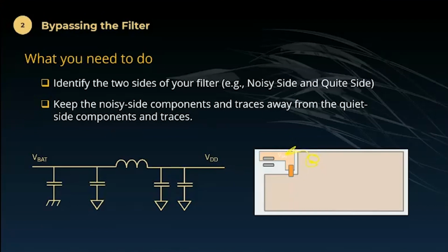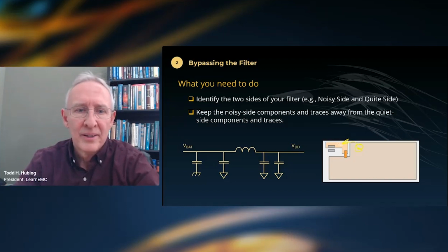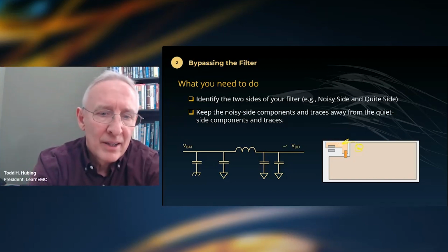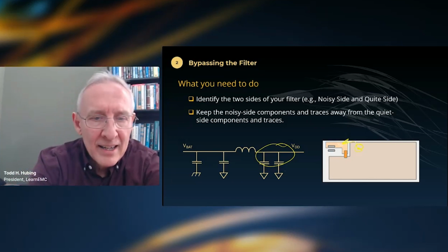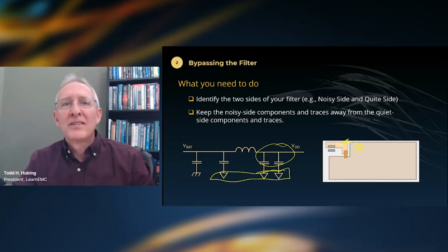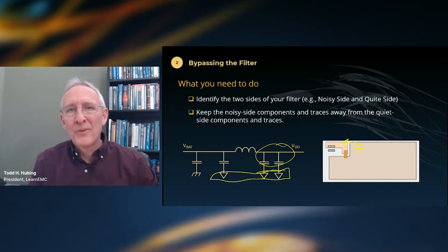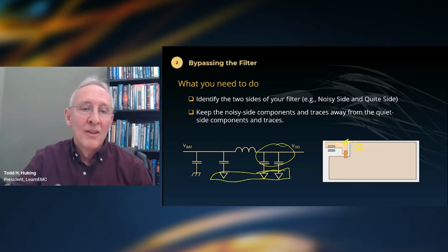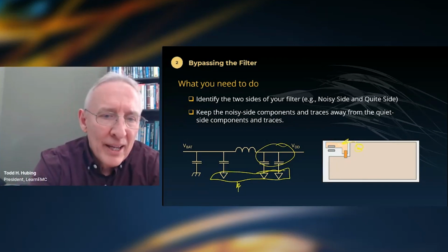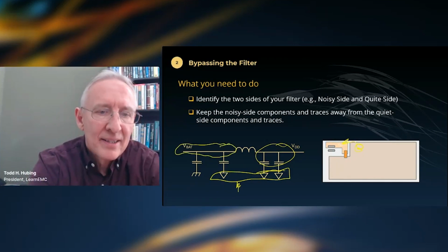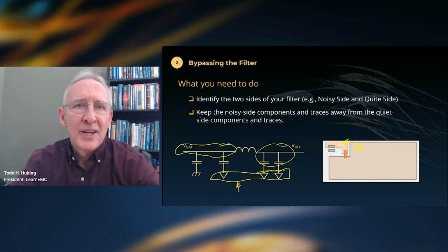Most boards, I'm sure you're aware, are much more complicated looking. There's a lot to look for. And so when I'm reviewing a design, what I will do, if you're using Altium Designer, is color every layer a certain color, like red. Every net on every layer is red. Then go in, and of course ground is neither on one side of the filter or the other. Ground is ground, so color your ground nets green, or actually color this ground net green, not all of them if you have more than one. Then go in on the side that has the fewest nets and color those a contrasting color like yellow.